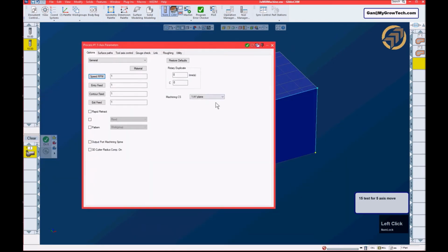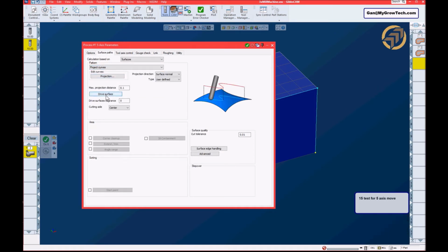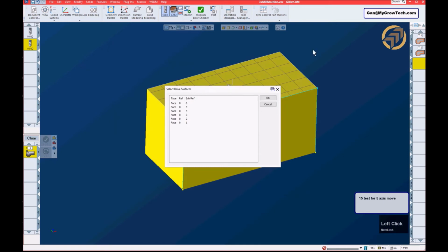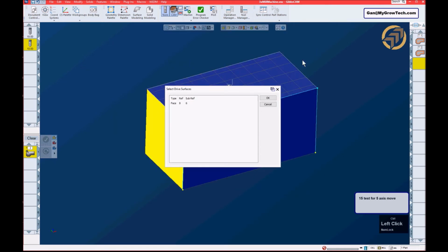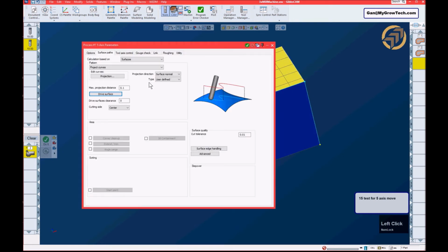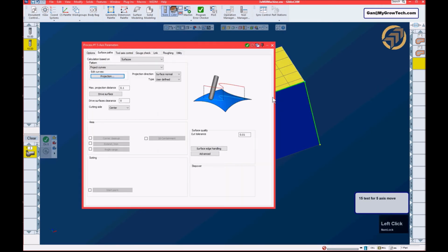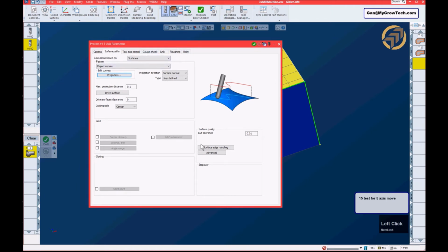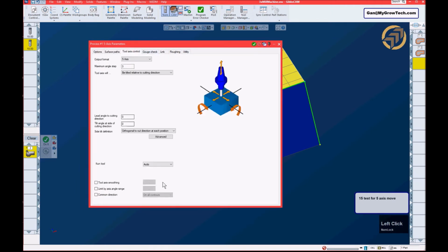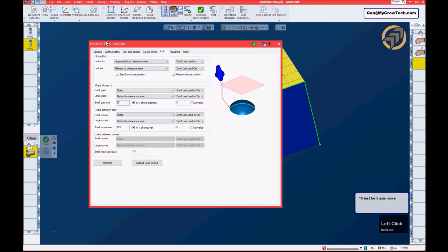Right, so I'm going to use the XY plane, surface path. I will use the project curve, and select the drive surface, use control key, and make sure on the face filter, control key to choose these 3 drive faces. Okay, and projection line, and let's choose this line here as my projection line. This setting is okay, default. Go check, no need. And this is okay.